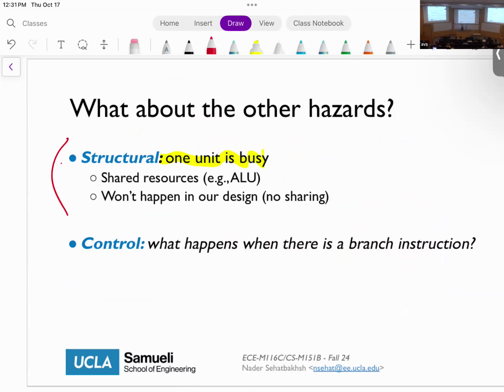But keep in mind that, for example, if I want to make the system more power efficient, then I could reduce the number of ports. In that case, I need another condition added to my hazard detection unit to stall the processor when it needs to read 2 ports of registers. So for example, if I have back-to-back R-type instructions, then I need to stall. If I have an R-type and an I-type instruction, I don't need to stall, right? Again, this is a trade-off between performance and other metrics, including power or area. But as I said, in most processors, you try to avoid structural hazards, okay?